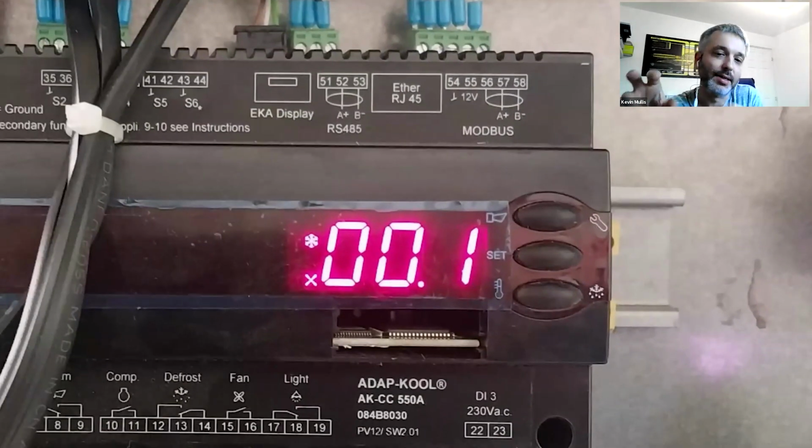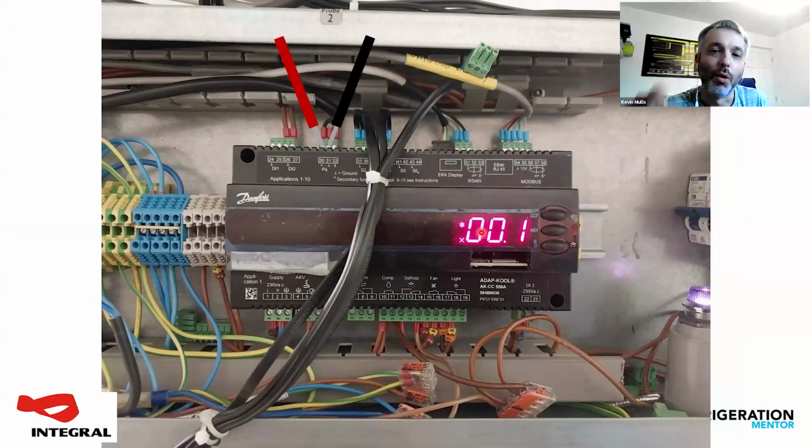And that'll either be your digital input configured as a run signal, or a parameter. There's a software version of it as well, parameter R12, which Danfoss call main switch. If you set that to 0, the controller will stop. All the outputs will go off. So yeah, if you've got status 10, something has told the controller to stop. That would be right there.